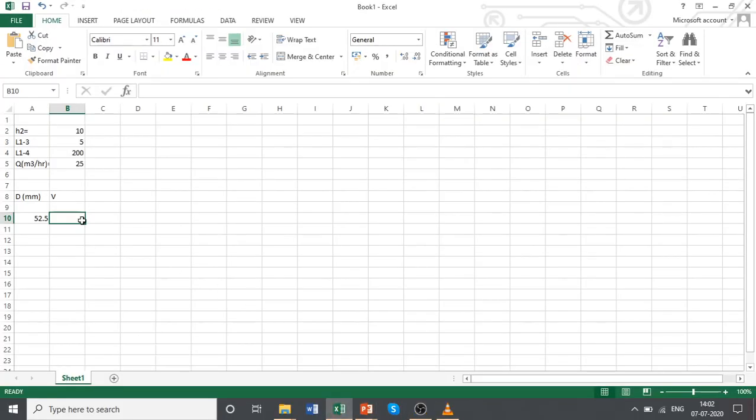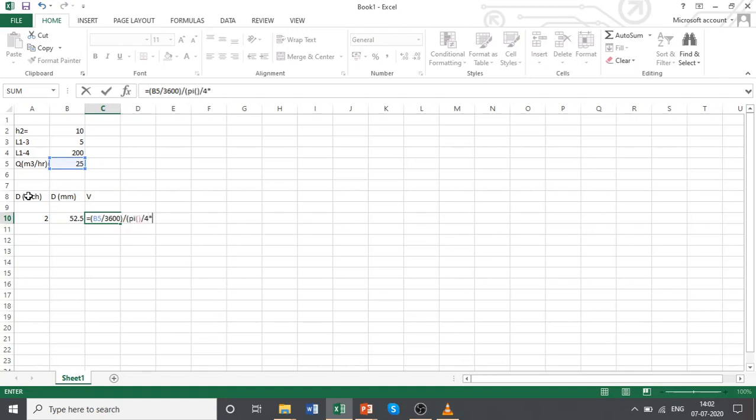I'm going to show you for one diameter. So what I have written: H2 is 10 meters, L13 is 5 meters, L14 is 200 meters. Flow rate, I want the same flow rate, 25 meter cube per hour. If we take different diameters, 52.5 is the 2 inch pipe. Let's just put that here, diameter in inches. So 2 inch. Velocity we can calculate from here: flow rate 25 meter cube per hour divided by 3600 gives meter cube per second, divided by pi by 4 multiplied by 52.5 millimeters, divided by 1000 and squared. So velocity will come out to be about 3.2 meters per second.